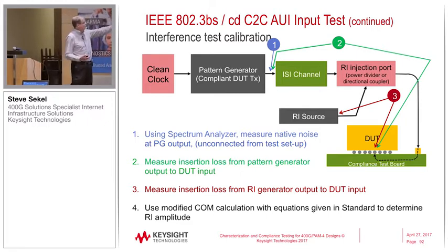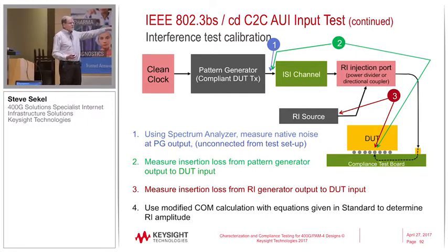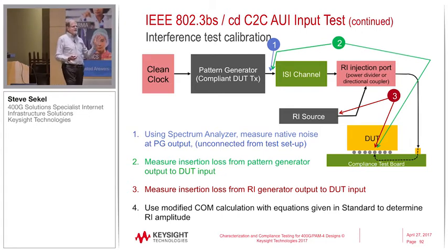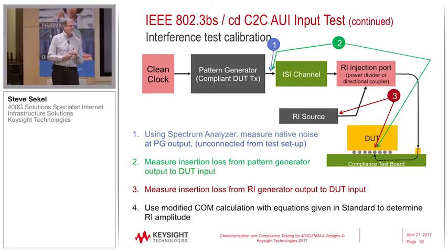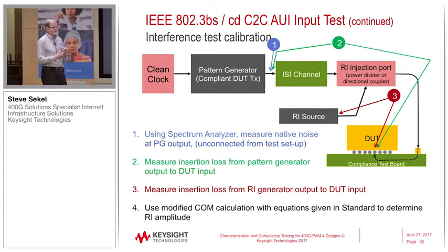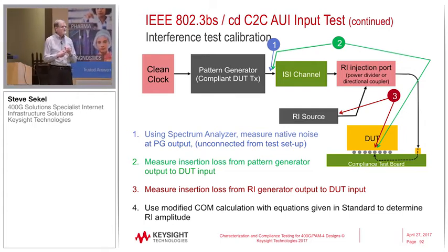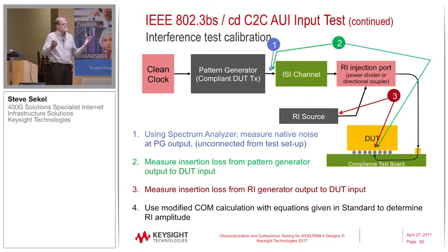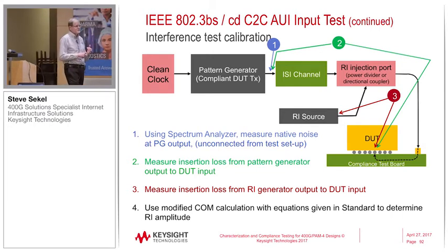So with all the channel in there and everything, they want to put the noise in to replicate the worst case transmitter plus the worst case channel. And I don't think you're going to get enough noise out of a transmitter to do that. It would take several transmitters. And then, who knows what the spectral content of that is, right? So this is a more standardized, repeatable test.